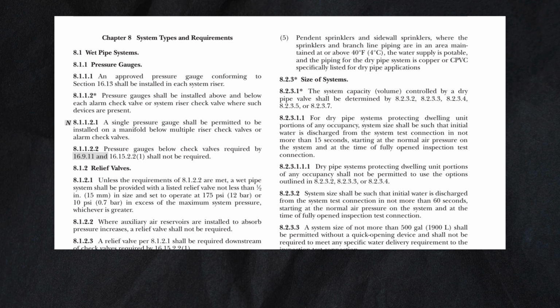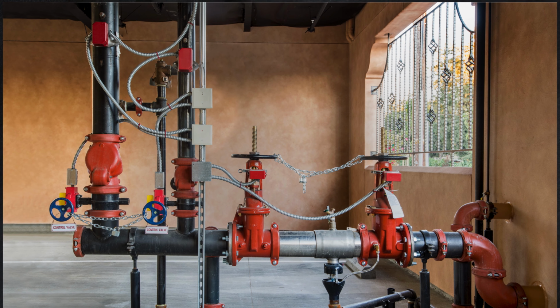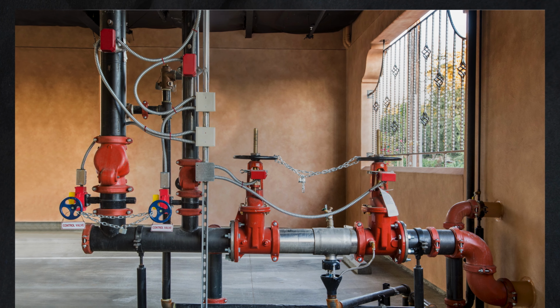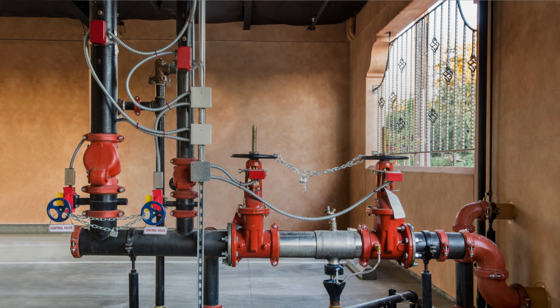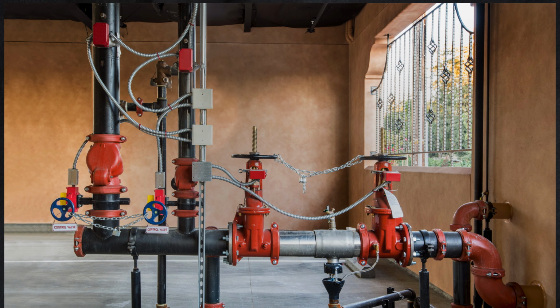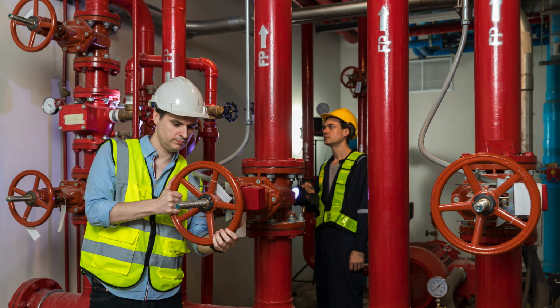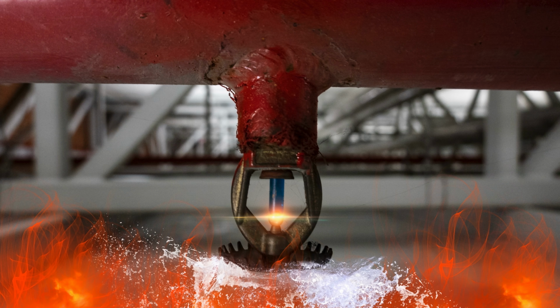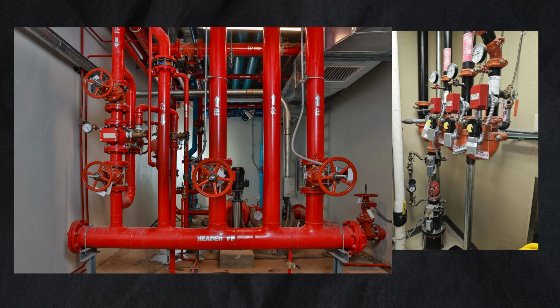When considering a fire sprinkler system, many opt for a wet system because it offers immediate protection by having water constantly available for quick activation during a fire. Its straightforward design and reliable operation make it a cost-effective choice with minimal maintenance needs. Wet systems are proven to effectively suppress fires, and they often lead to reduced insurance premiums due to their effectiveness in mitigating damage.